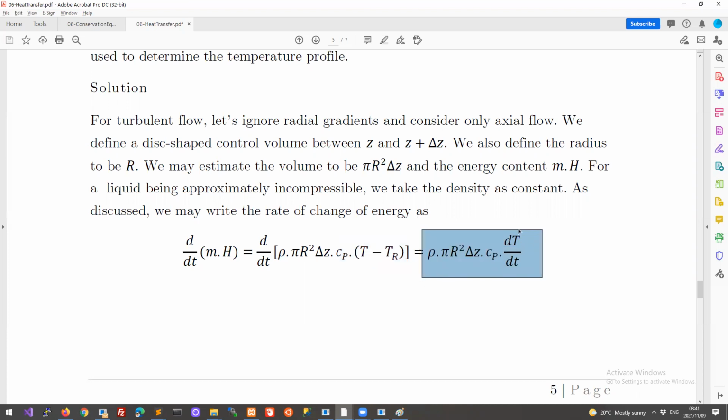So the only difference between what we saw earlier is that we have now expressed the mass in terms of the density here. And we need to do that because we need the volume and the area and all those things together in our balance. We know that when we write our balances, we get some nice cancellations and we can develop our derivatives and so on. So we want to work in terms of the geometry. So that's why we have to work with the density here.